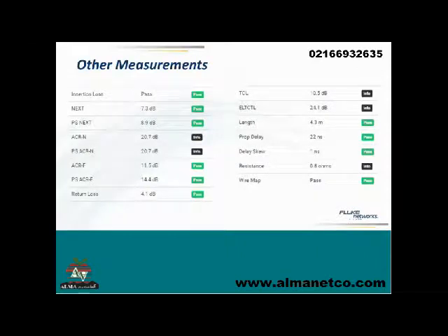Now, there are a lot of other measurements. I'm not going to talk about them all here because they are not as common, and many of them are related. In fact, all of the ones that say near-end crosstalk, ACR-N, ACR-F, all of those are basically different crosstalk measurements. I mentioned there are 6 different types of crosstalk measurements, and those are just basically variants of a crosstalk measurement. Insertion loss and return loss relate to how much the signal degrades as it travels over the distance.